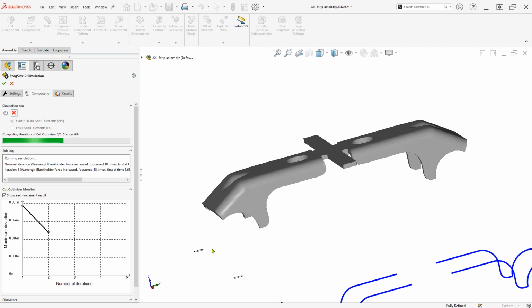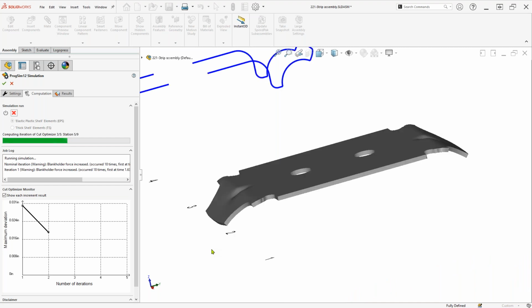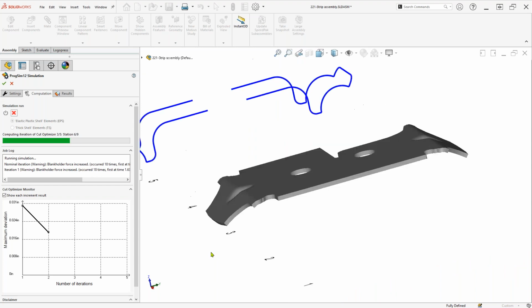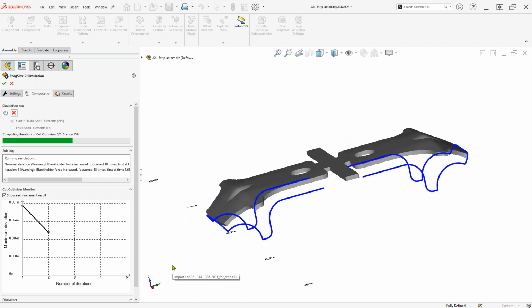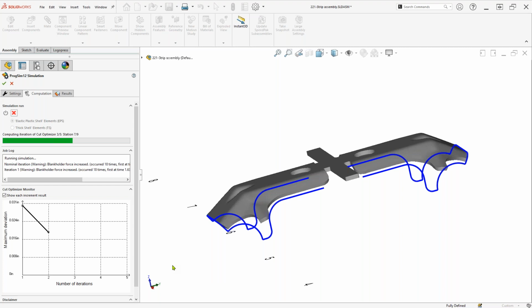So most of it is all of the tooling that you actually have pre-built in the strip layout beforehand, your cutting punches and your forming punches. Beyond that, it's ideally tested material data going into it. It's a bit more than the tensile strength and that kind of thing that SolidWorks has. So it's a bit more involved getting material into the database for it, but we've got, I think, something like 100 materials in here already. And that's going to cover quite a number of things.